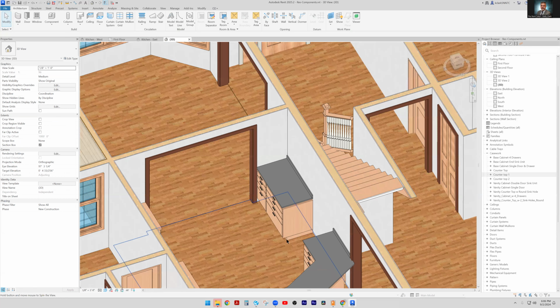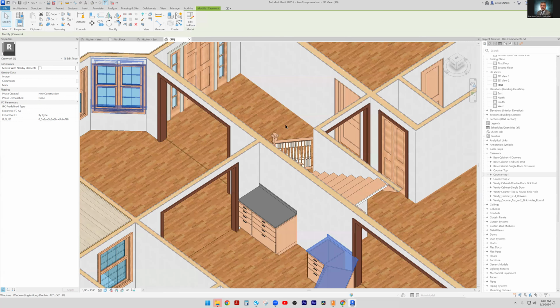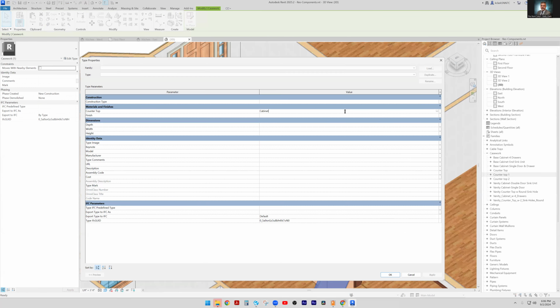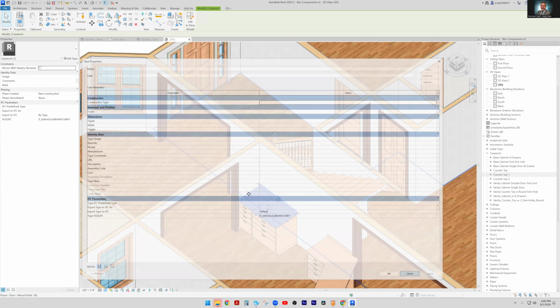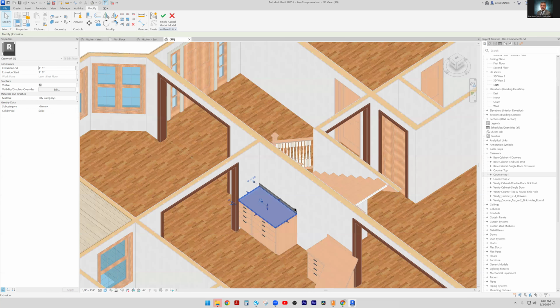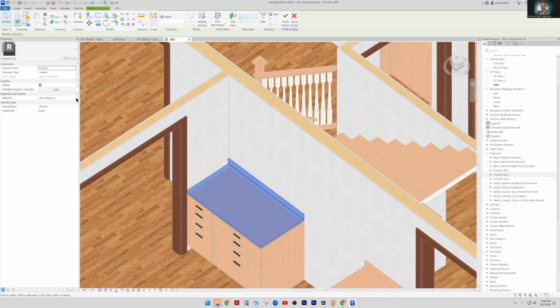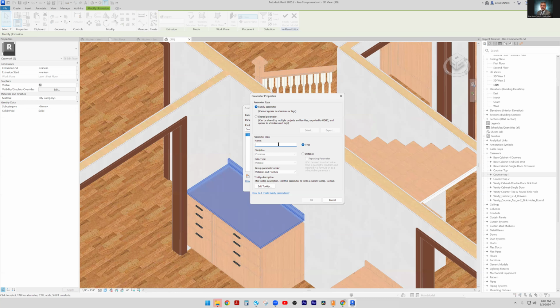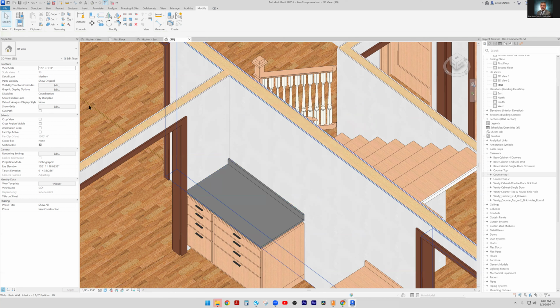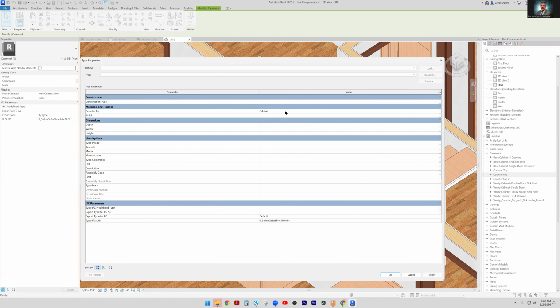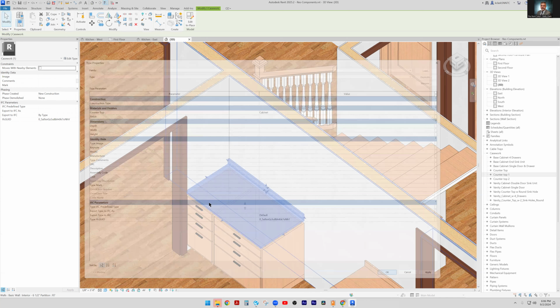All right. I didn't add any material to these guys, and that's why they're gray. So if I go into the type properties, you can see that I did give it the opportunity. I still have my cabinet material on my paste, so I'm just going to paste that on to each of them. So edit type. I hope I forgot to do this one. Edit type, select these two here, give them the material association parameter. So I'll counter. So okay. And finish. I'll select it, the type, and say okay. All right, cool.